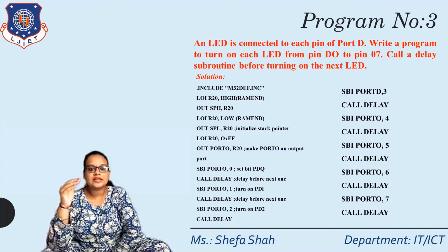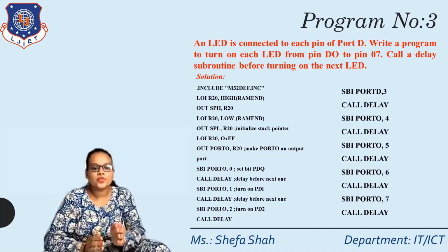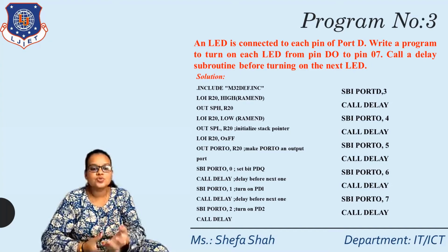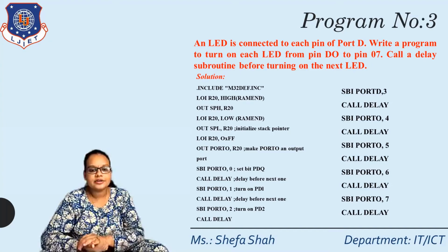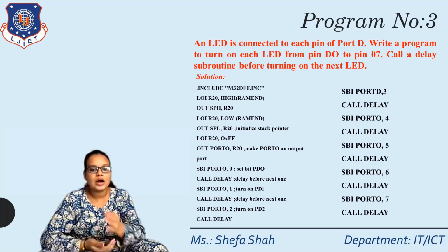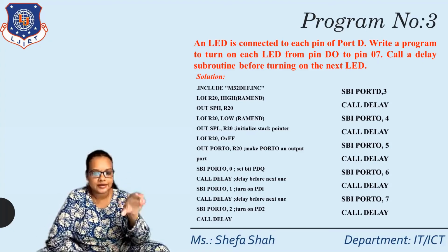So as you can see in this program, .include, again m32def is included, right? Here, we need to call this delay, so we need to initialize the stack pointer. So using the LDI instruction, we are setting the stack pointer high and stack pointer low. So these first 4 instructions, that is LDI R20 high, out SPH R20, and LDI R20 low, out SPL R20. So we have initialized the stack pointer with an address, right?